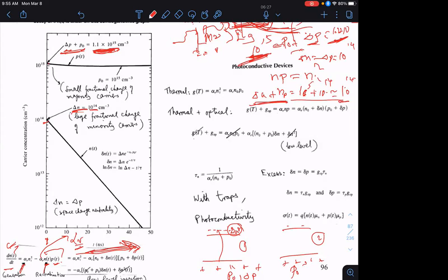Don't confuse this with the absorption coefficient that I showed previously. Although ultimately they are related, it's a different proportionality constant. Now there's also the inverse generation process, whether you like it or not. Why is that? Well, remember we said that we are surrounded by the walls of my room, which is at room temperature, and that's going to constantly emit black body photons, right? That excite carriers, electron hole pairs, but then after a few nanoseconds, those electron hole pairs recombine and give off black body radiation. So this is black body photons, not the laser light that I'm shining on top of it. Okay.